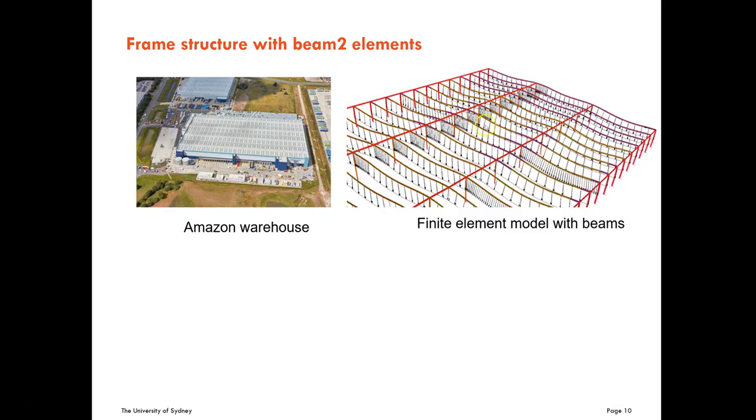So it's a long span beam that you have to model with special care to avoid large deflections or collapse. One of the techniques used for these long span structures is pre-stressing or special bracing.